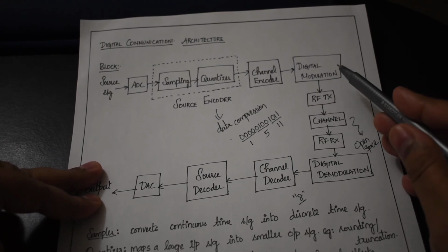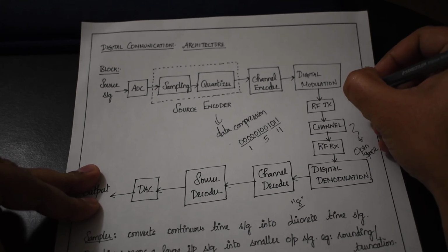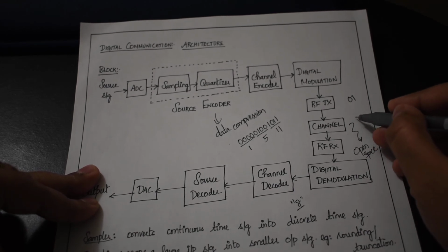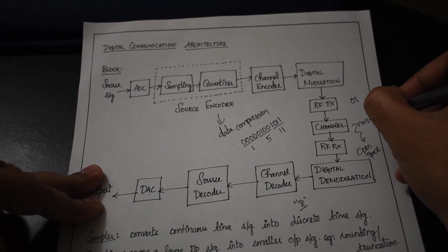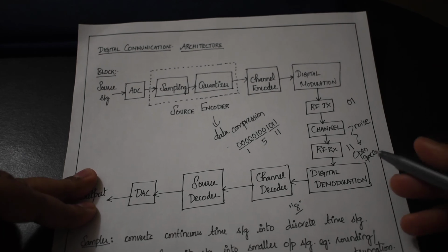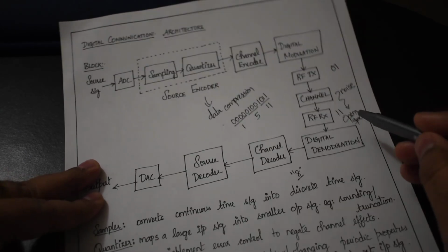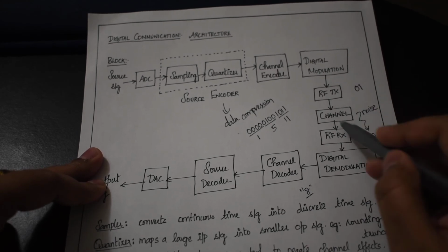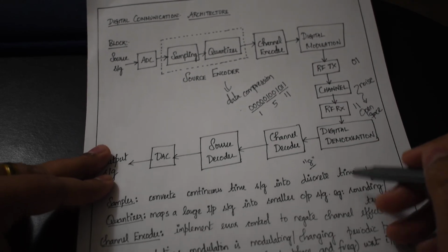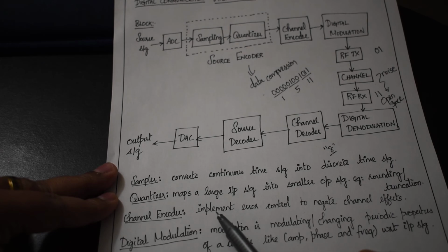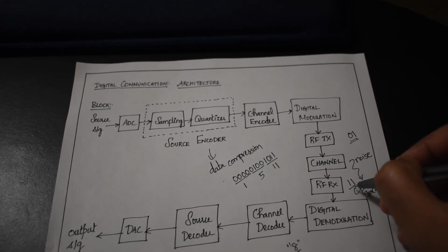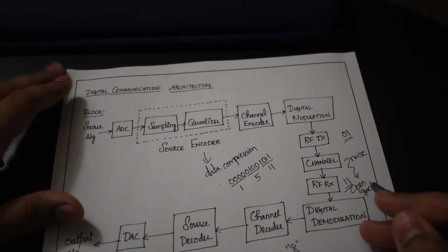It is open space, or the air, the medium in which we communicate. So when we are transmitting some data through this channel, let's say 0 and 1, because of the noise that is inherent in the channel, we might receive it as 1 1 instead of 0 1. This type of error should be rectified, or the system should be able to recognize what it has sent in order to rectify what digit it has missed. So in the channel encoder, we implement error control mechanisms in order to escape from these channel errors.